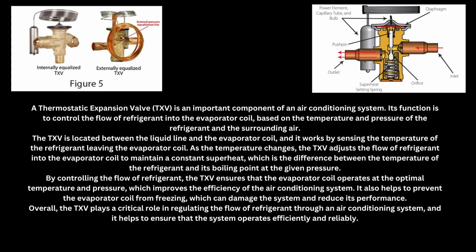Well, the thermal expansion valve is designed to initiate a response because of the added heat load. It can respond and adjust and allow more refrigerant flow to come through to absorb that heat load to keep your home at a cool temperature. So then, if you maintain 76 degrees in there, it is more efficient to keep it there. Sometimes it might go a degree above that, maybe a degree and a half, but it still will keep your home at a comfortable level.